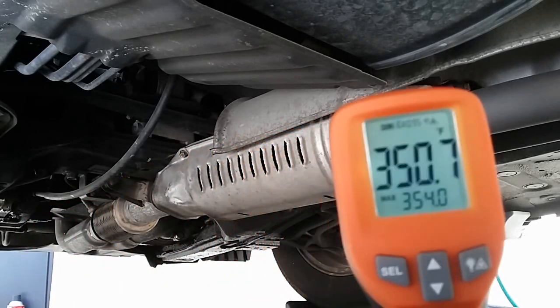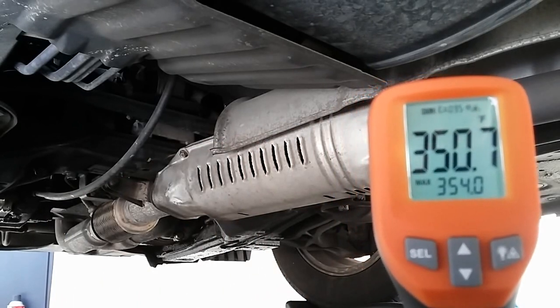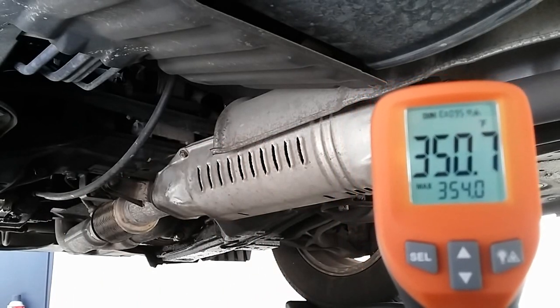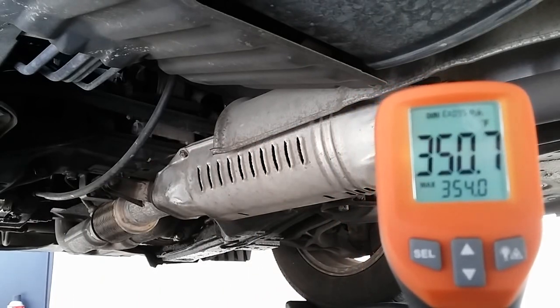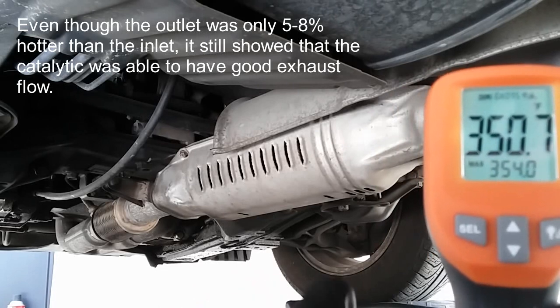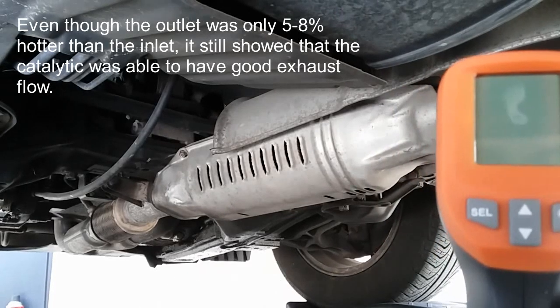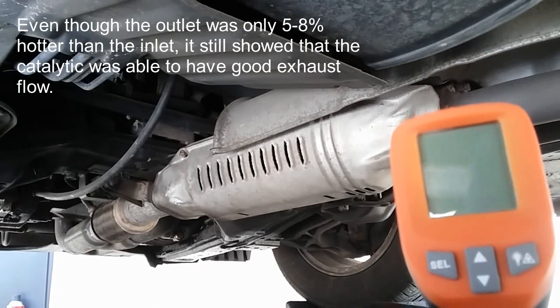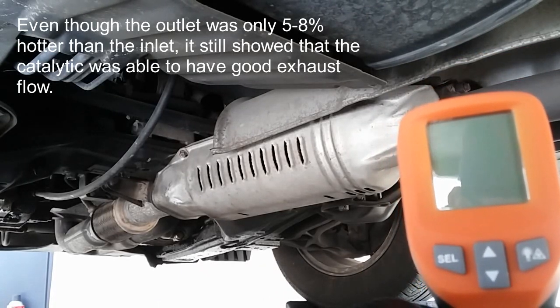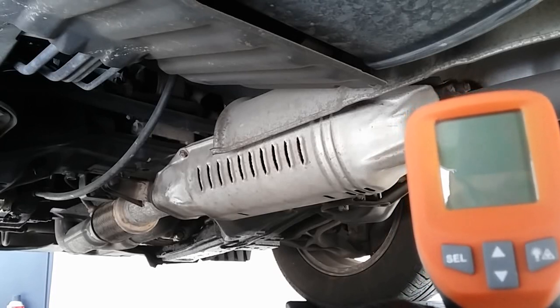So this is method number 2, which I use to diagnose this P0420. So far the catalytic is starting to show signs of going out, but still the outlet is showing that it's hotter than the inlet, which is still good.